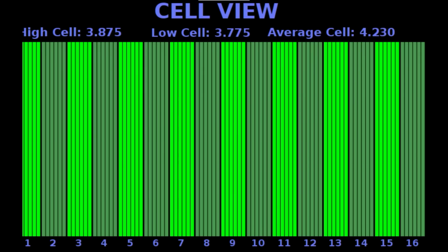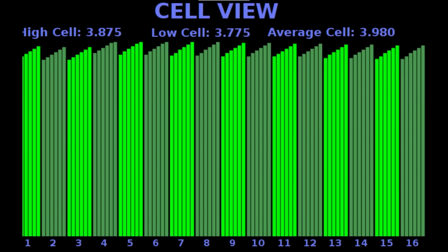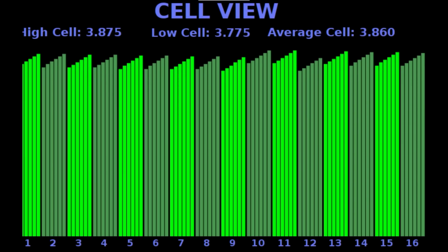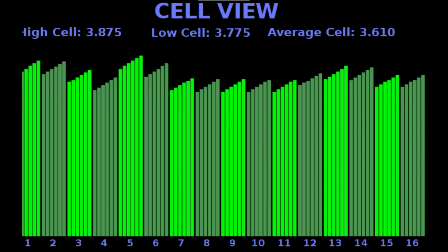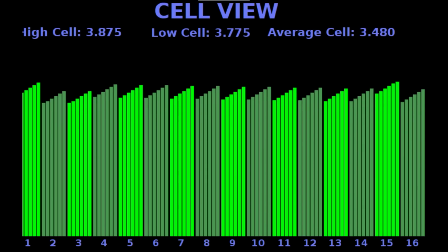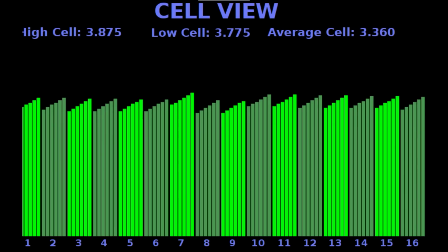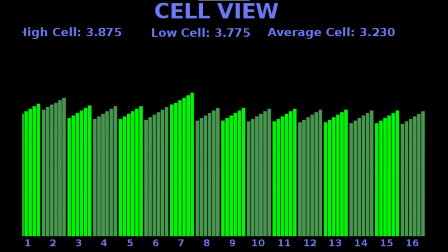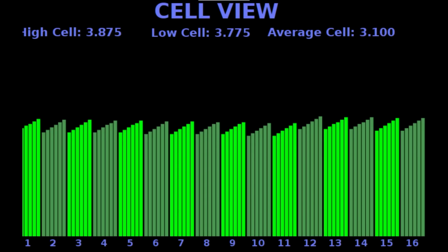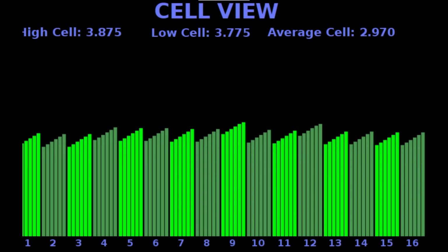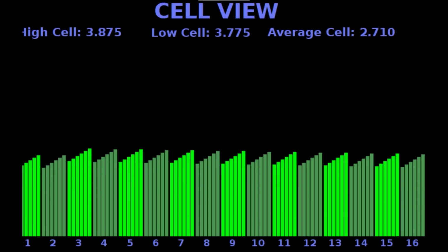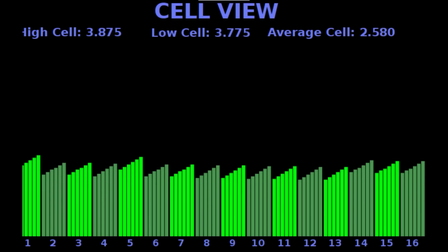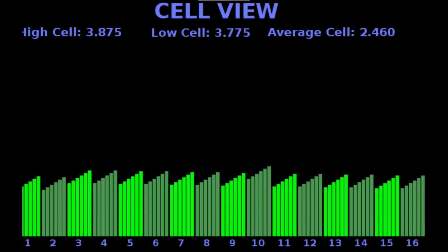Well, this is kind of an interesting, if crude, protocol, and it's based on the philosophical concept of, oh well, I missed some data. There'll be some more along here in a little bit, and plenty where that comes from. And so devices on a CAN bus simply transmit often, and the other devices that are listening for that data get it when it gets through. And if you do it enough times a second, enough get through that you can operate.